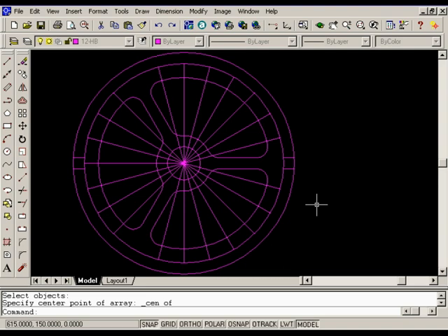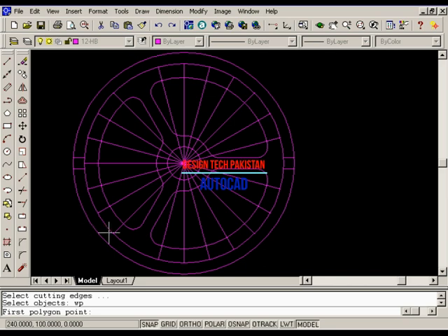Selecting objects with a fence line. On the Modify toolbar, choose Trim. Use the Window Polygon Selection method 3 times to select the 3 elements of the array.